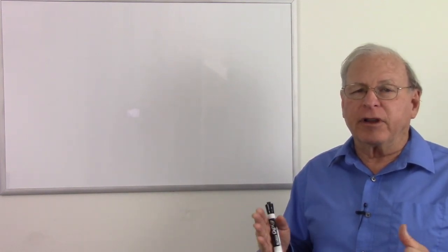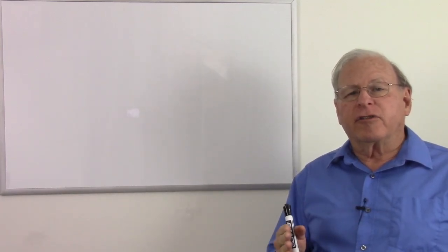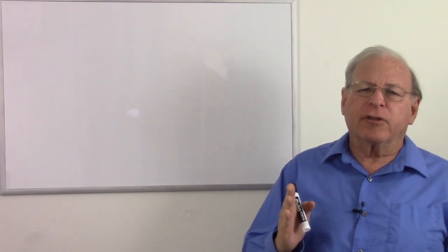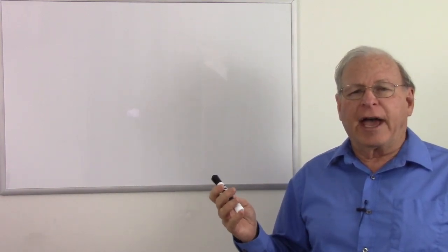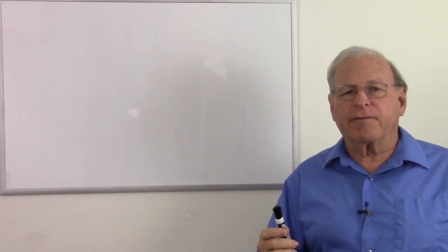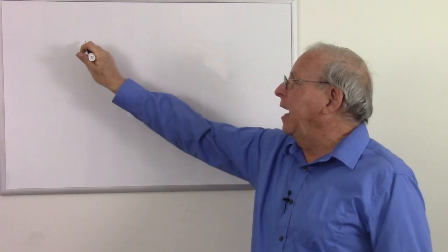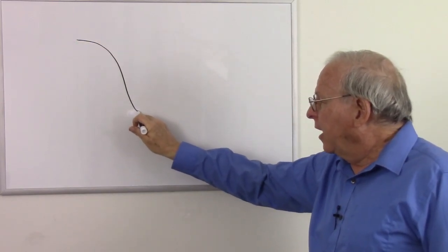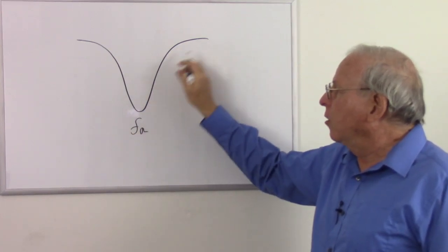And if we put them together in series, we find that capacitor and inductor in series will pretty much look like a short circuit at a particular frequency we call the resonant frequency. But above that frequency, it's going to have a high impedance, and below that frequency, it'll also have a high impedance. So the impedance of an inductor and capacitor in series will tend to go down at a particular frequency, the resonant frequency, and then go back up.